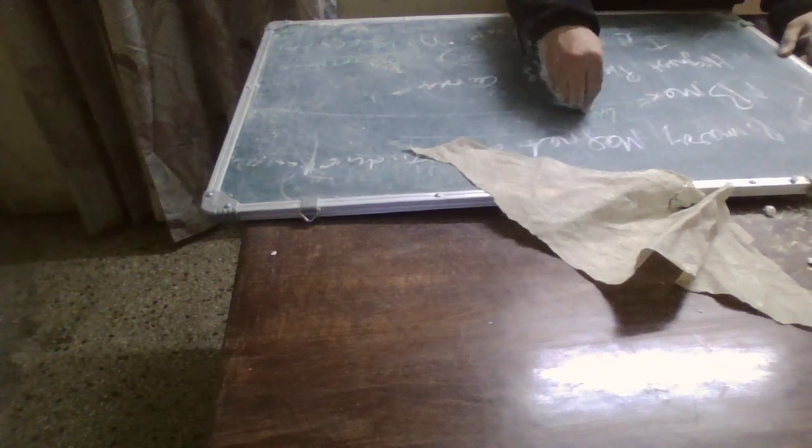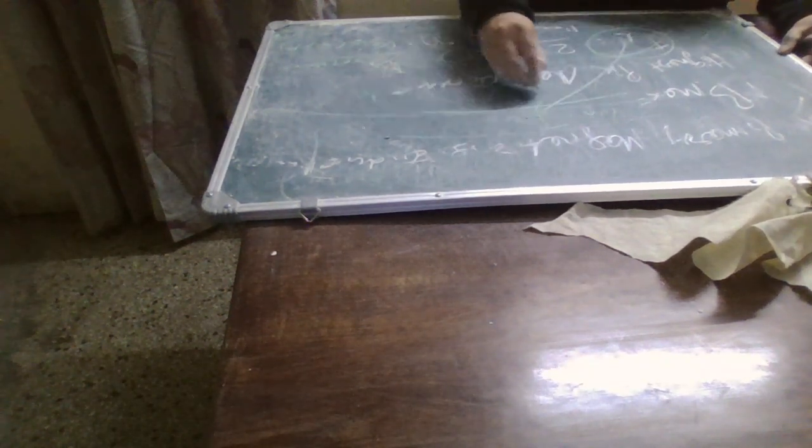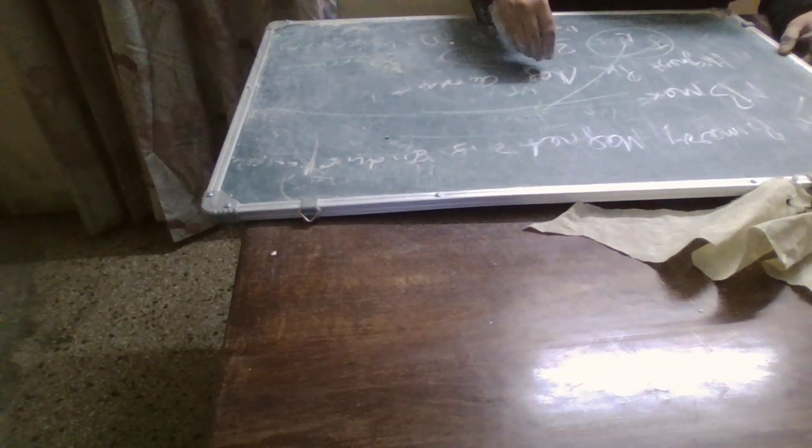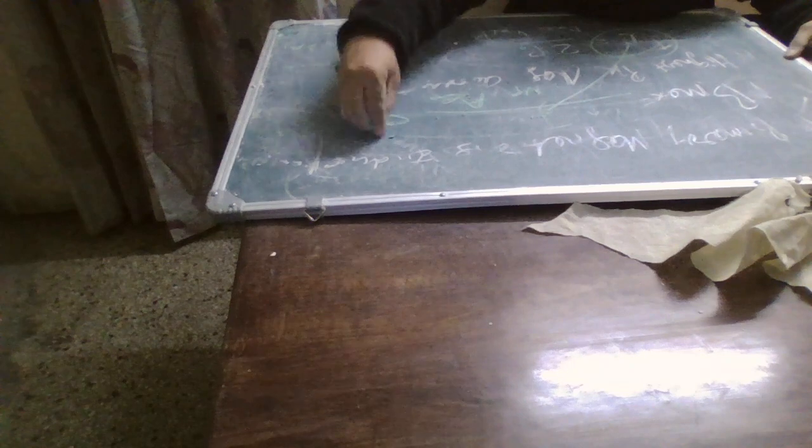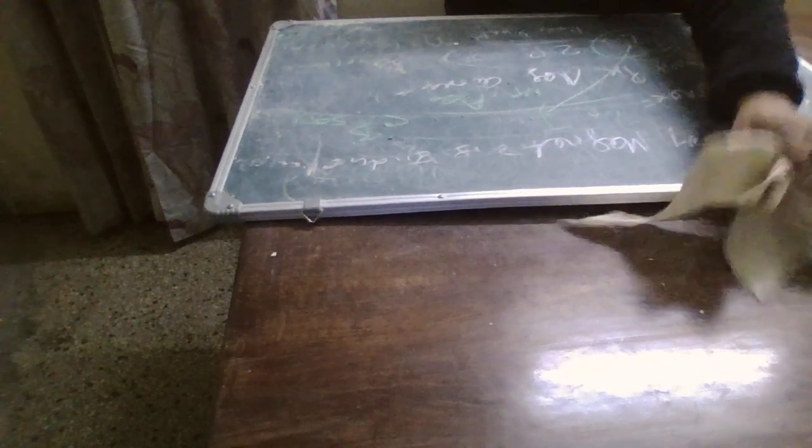So the Bmax would be equal to Lm, which we have calculated here, upon NP, number of primary turns, cross sectional area of the core AE, and it should be below the saturation limit of the magnetic core. Now we have taken AC flux density.